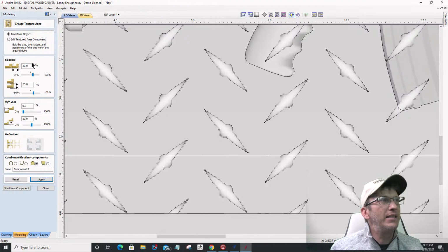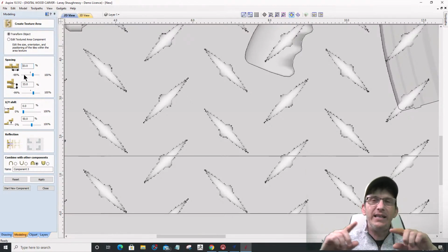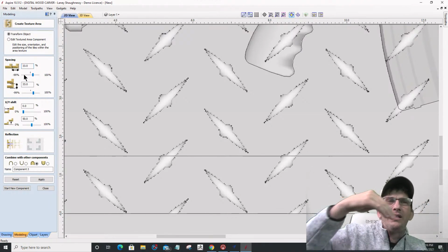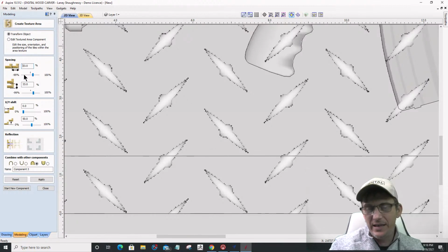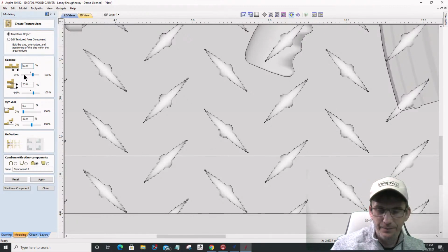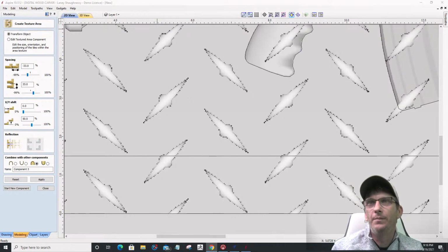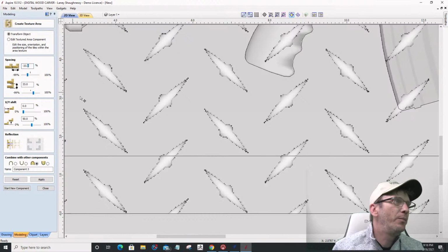And that's because on my spacing here, that spacing I did on the X, I need to go backwards the other way, right? So it needs to be a negative 33.3%. And I want to put that 0.3 in there. Let's see if the software will allow me to get my 0.3s, and I want to click apply.